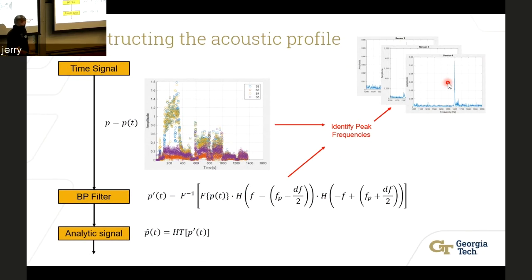We discovered, and this is just based off of looking at hundreds of amplitude frequency plots, that any bandpass filter frequency below 10 hertz was not able to capture the entire peak of one mode. So we established empirically some lower bound for our bandpass filter frequency, but it was empirical. So I still think one of the improvements for this program could be some way to optimize the bandpass filter frequency. Somehow have the program ask itself, is this bandpass filter frequency going to properly integrate at this peak frequency and capture the mode, but also if I decrease it, is it going to change the results by a lot?